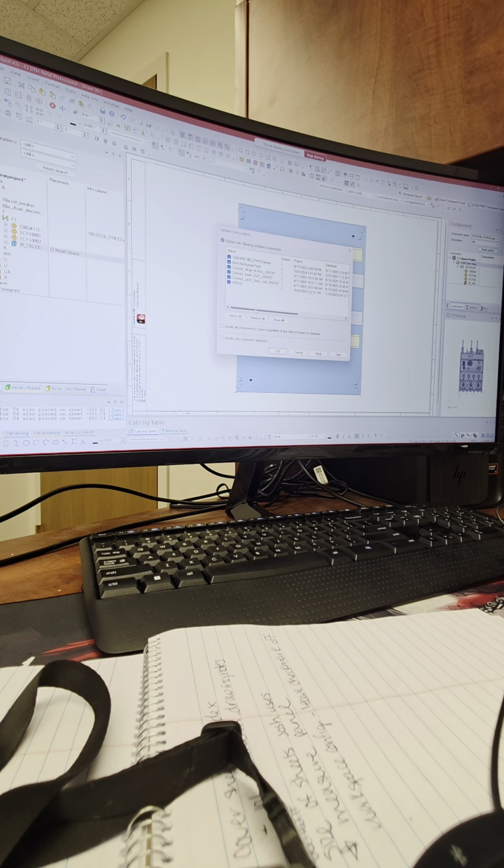So anything that you see in this list was modified, let's just say on 9/18, since the last edit was committed to this project. So if that was all intentional, and you say, okay, I do want to see all these changes in my project, then you can just click OK, and it's going to update all of these, whatever, 5-6 parts that you edited in the library, and commit them to your project.